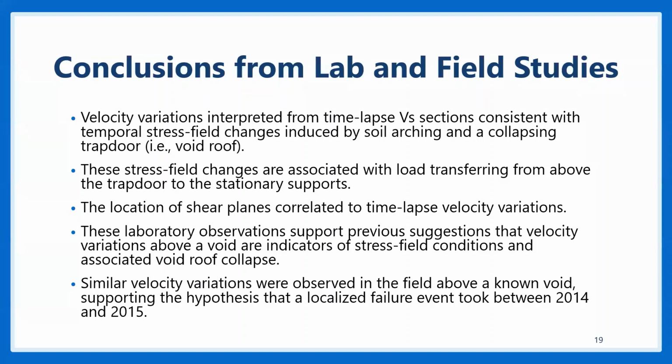The load transfer happened because we moved the trapdoor vertically downwards, so we changed the distribution of load and induced soil arching. That soil arching was able to be observed as changes in velocity. And we were able to not only see these changes in velocity, but also see in real time the development of shear planes or failure planes, which we then correlated to each other.